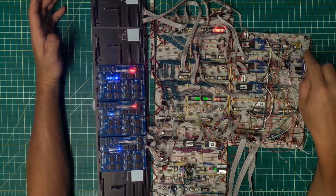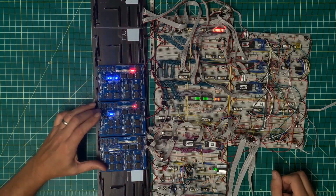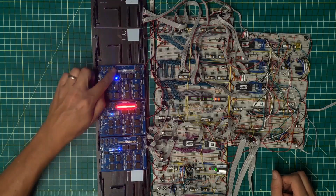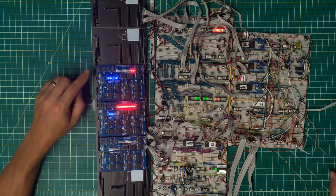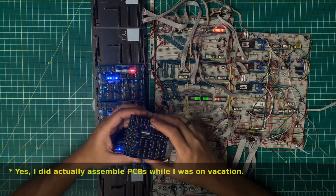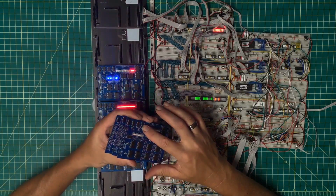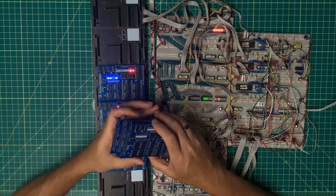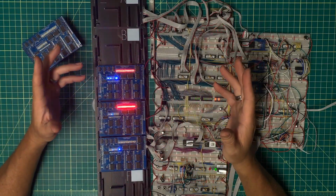Now, once again, I have not fiddled with the timing over here yet, or the timing down here yet. I have 2 more registers that have been built and tested that I need to upgrade to use the new counter ICs. Plus, while I was on vacation, I built 3 additional registers. Now, these have not been tested. But before I get into that, I may as well go ahead and replace those. So I've got 5 boards that I am going to upgrade to the new counter ICs.